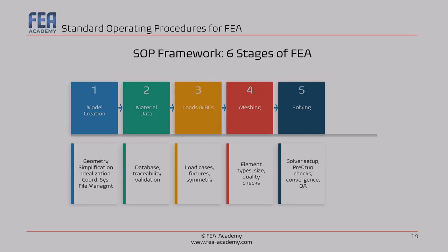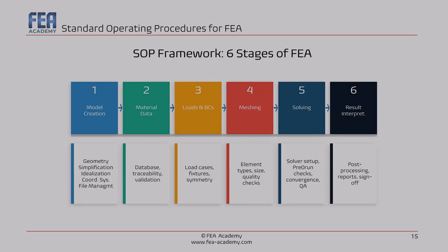The 5th one, stage 5, is solving, for sure. At the end of the day, we need to solve the solution. So we have the setup of the solver, the pre-run checks, the convergence monitoring during the solving. And stage 6, the last one, is the result interpretation: extraction, acceptance criteria, the reporting.